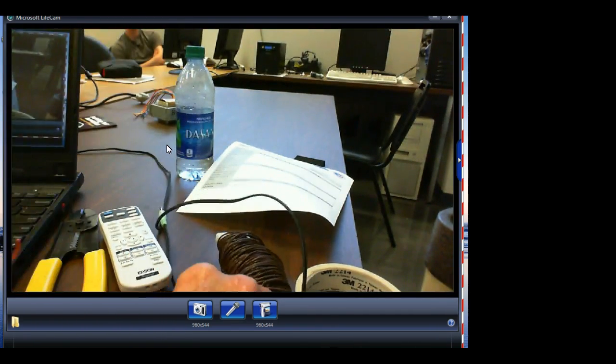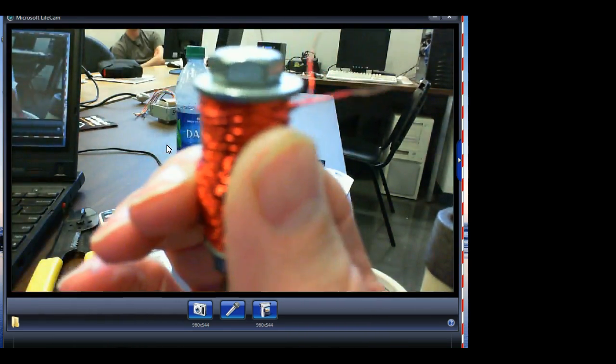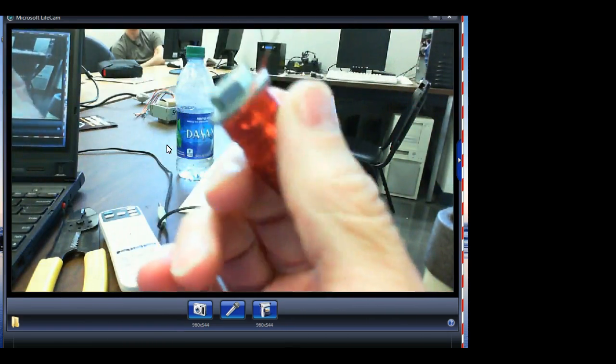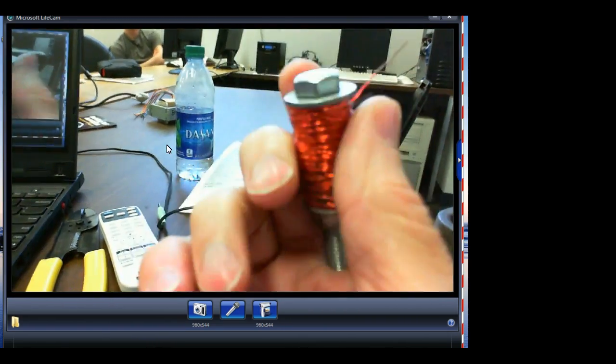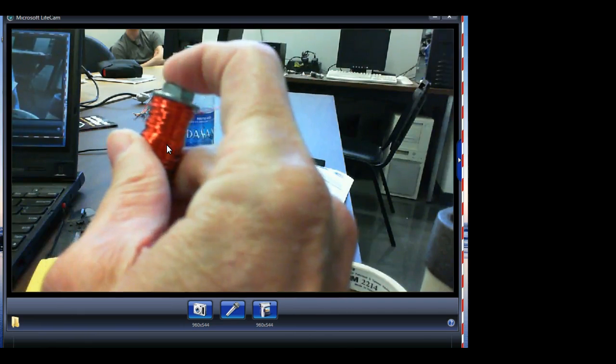if I use a big chunk of metal like that, that's a conductor. And AC would induce a voltage into that conductor, and it would act like a short circuit. So the transformer would become extremely inefficient. We don't want this metal to be a conductor of electricity. We want it to be a conductor of a magnetic field.